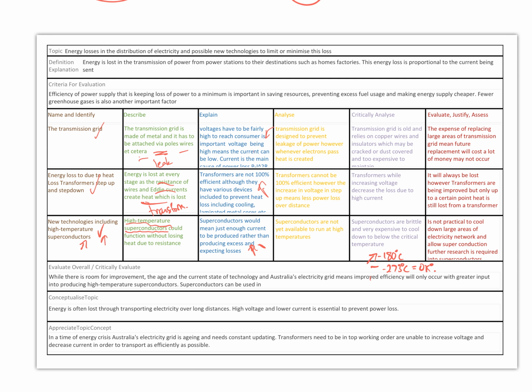For our analysis, we can talk about the grid, its design, and that it leaks power. We have to put a lot of energy in at one end to get out what we need. We use transformers all along the grid. Step up, then along the grid, then step down, substations, step down again for houses to make sure we've got the right voltages. When you step down on a transformer, remember the current goes back up a bit. Power in equals power out. VI equals VI, remember. The efficiency of transformers, the loss, you can mention eddy currents there.